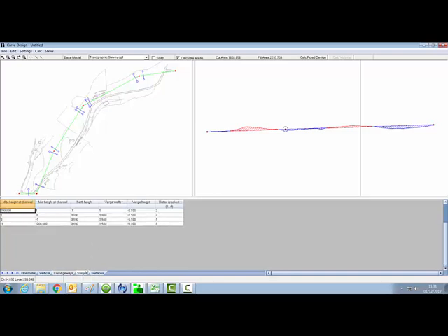For the verges and batters, these will depend on the height of the road, whether we want a curb, and the verge width and verge height and the batter gradient, depending on the height of the road, so that could be cut and fill. We can also apply a template to each part of the road to allow for the imported materials. So I can enter these here, the amount of resoil on the verges, the amount of resoil on the batters.